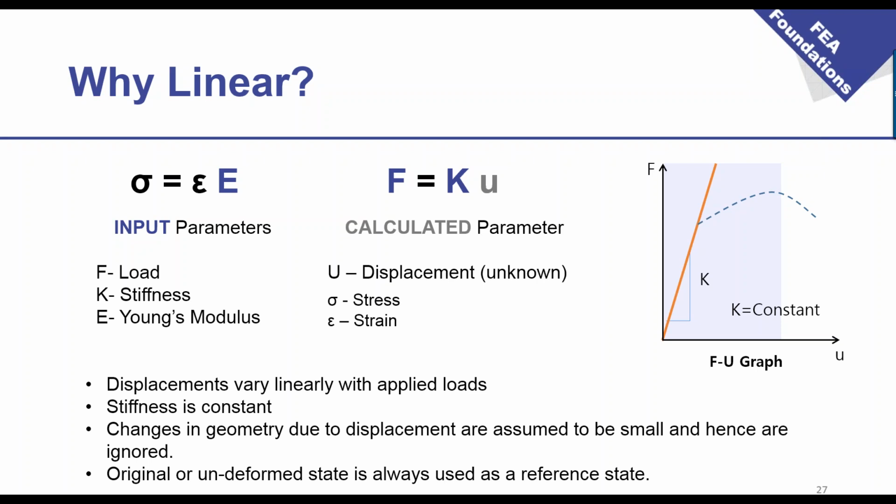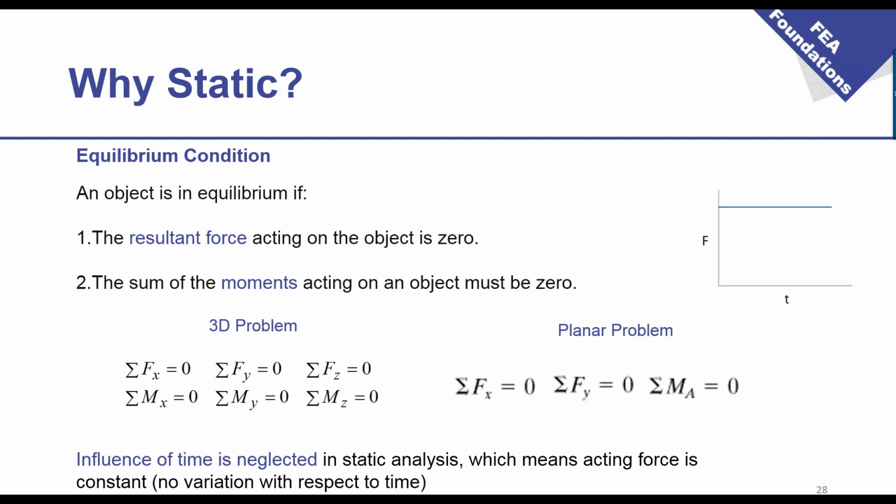And this type of loading was the loading that I actually used. K means stiffness, and it comes from the material property and your mesh. So this is the resultant of that, and we are looking for U, which is displacement, and based on that the software is calculating other output vectors like stresses, strains, and other data.